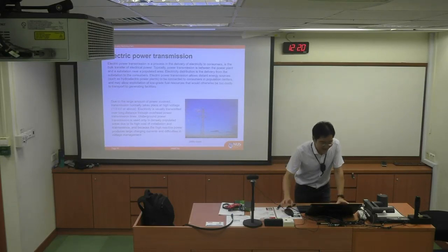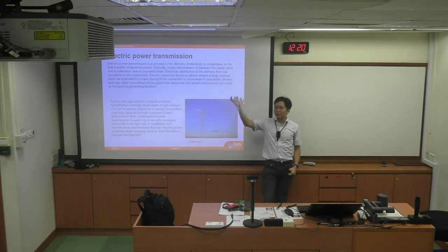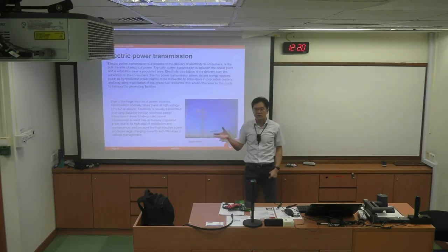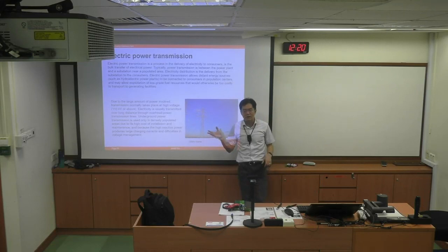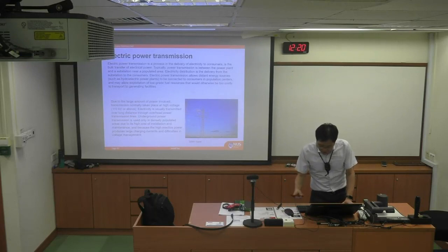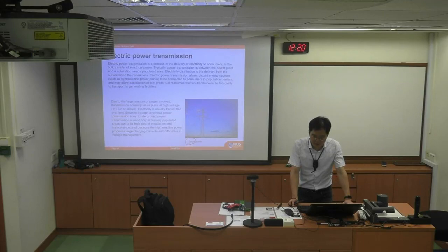Anyways, electrical power transmission is used to elevate the voltage and then transmit. We'll come back to that, there's a good reason for it because of the efficiency. Now, this is one of the reasons why AC took over DC. Although the electronics are using DC, the transmission of power and the appliances still use the AC signal because it's easier to boost up the voltage there. All right? So the tower that you're seeing over here is using 500 kilovolt, and that's really, really high.